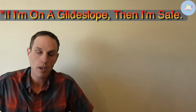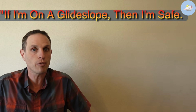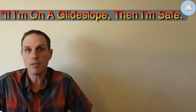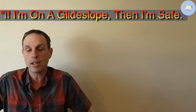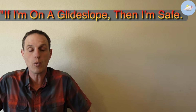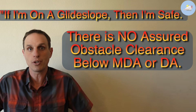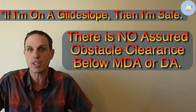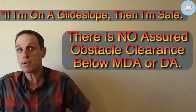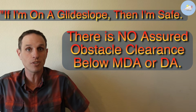The next argument I've seen is, pilots assume that if they see a glide slope, then that means they're safe. And this isn't the case even on ILSs and LPVs. Like we've talked about, when you go below decision altitude, there is no assurance of obstacle clearance. So applying that same logic to MDAs, again, the FAA and Garmin are being consistent.